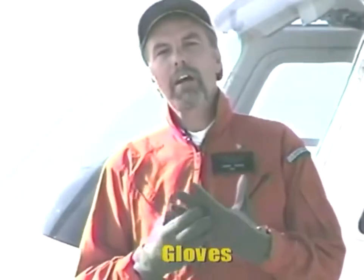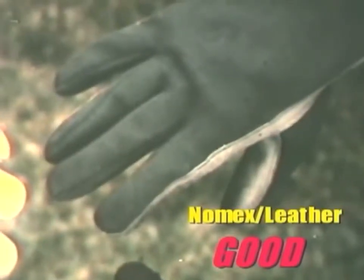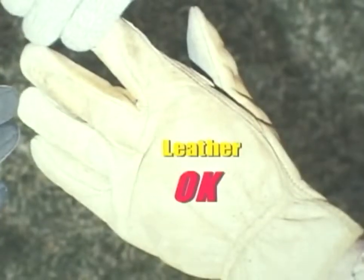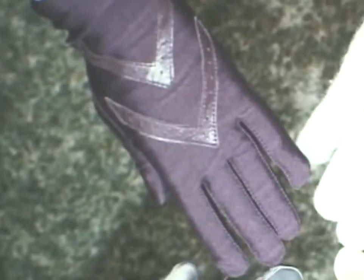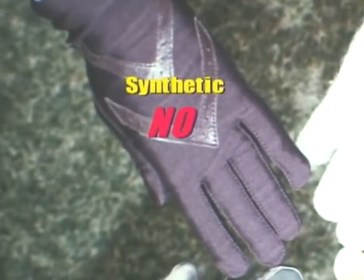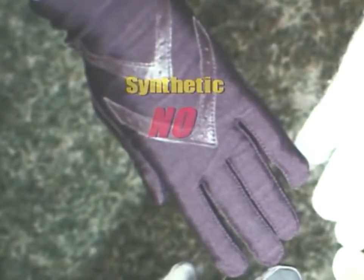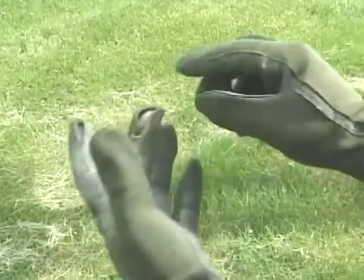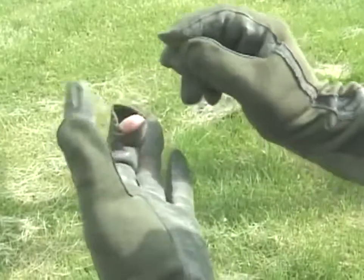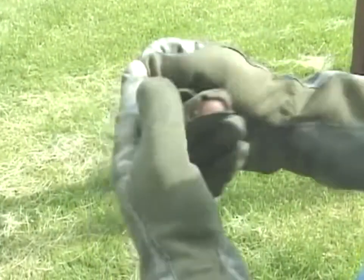What about gloves? What I've got on here is probably about the best you can do, and that's the Nomex and leather combination flight glove. 100% leather works very well too, offers good protection. What you do want to avoid is a synthetic-based glove, something that in a post-crash fire may burn and melt. Even 100% wool is not going to offer the protection you need. Also, if you're going to wear the gloves, make sure they're serviceable. Check them for holes, torn seams. If they've got any kind of that, they've lost their integrity, and they're not going to offer you the protection that you need.